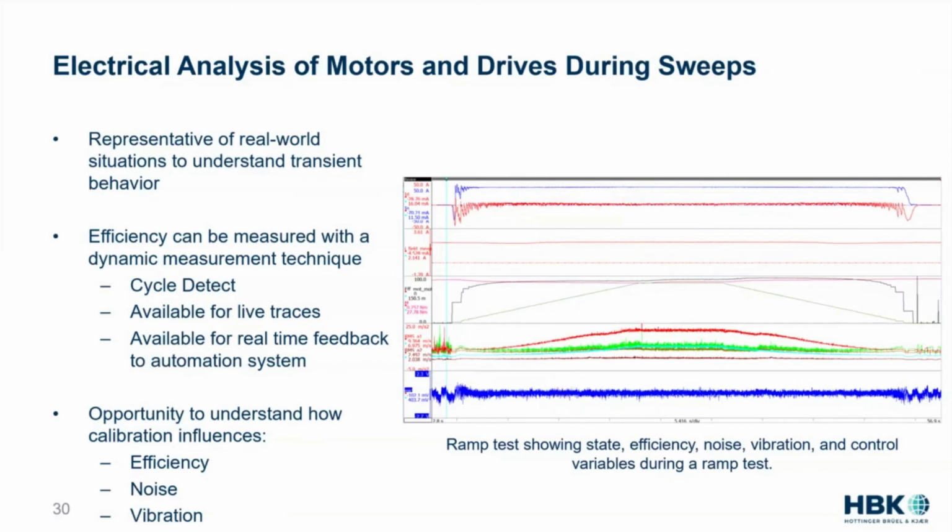And when you start having all of these things, let's say you have an issue in vibration. If you want to go back to your group that's doing the electrical side, you can give them the full picture. You can say, I had a really bad vibration. Here's my torque. Here's my speed. Here's my field current. Here's my voltages and currents. Replicate it, fix it. This is your problem now. But it makes that communication consistent between groups.